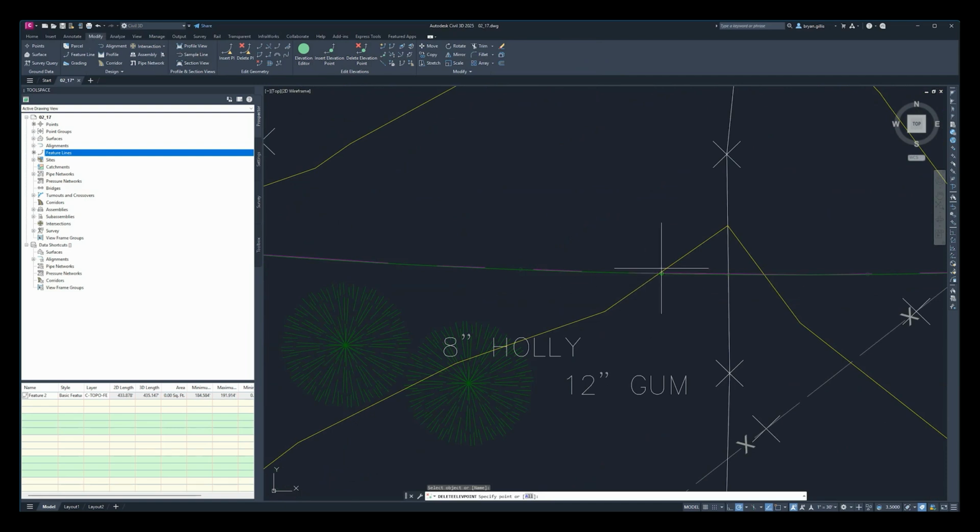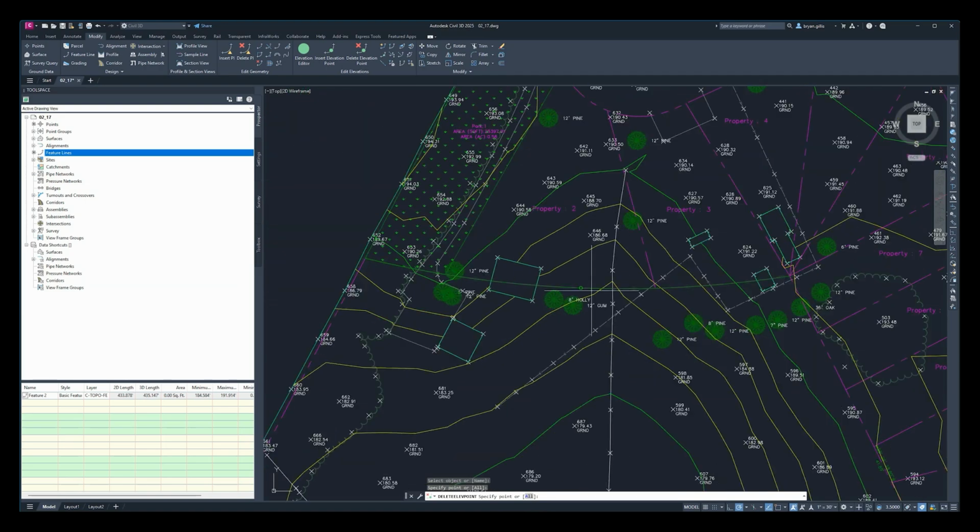So this is the point that I created. If yours is in a slightly different location, that's fine. Just identify it and delete it. We've gone over methods for figuring out exactly where the points you create are. So do that, click it, and just like that, it's gone. Do know down in the command line, we are specifying individual elevation points to delete. If I were to put in A for the all command with this selected, it would delete all of the elevation points along this line.